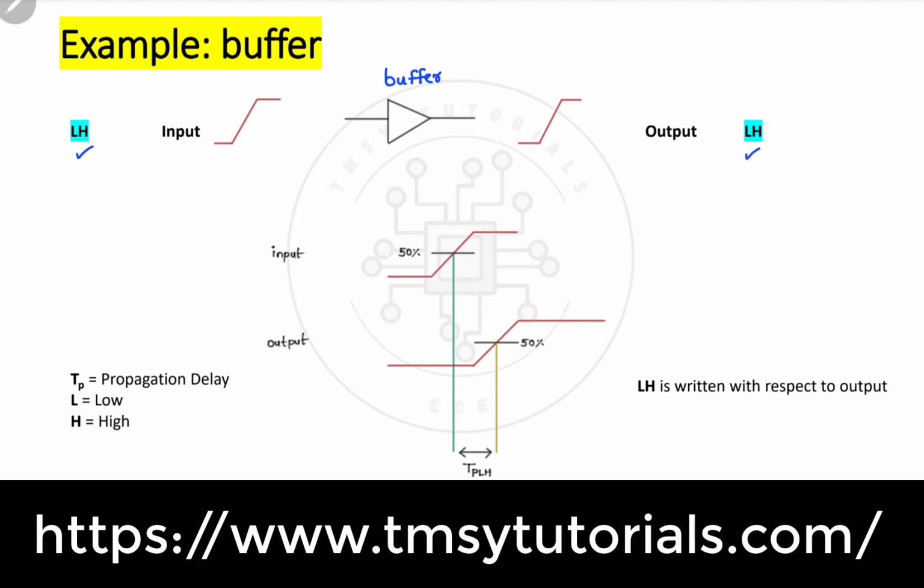Here you need to remember these key points. Some of the terminology I have mentioned here. L means low, H means high, TP means propagation delay. Let us analyze this by taking a waveform. This is the input which I am applying and this is the output which I am getting. Here I have taken 50%. This is the input threshold PCT rise. PCT is nothing but percentage. So I am taking 50% here.